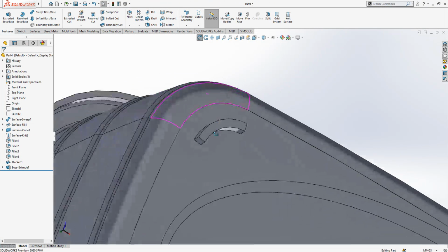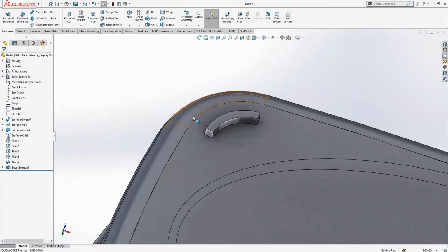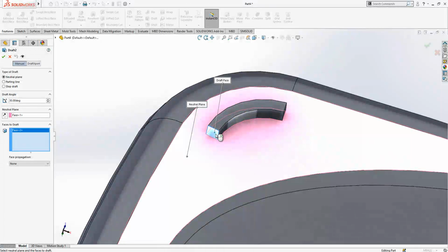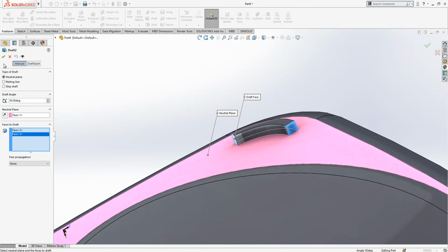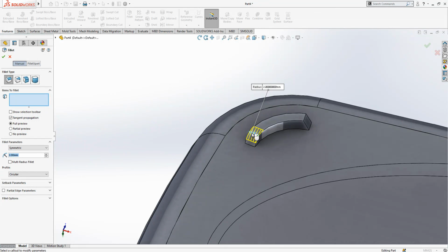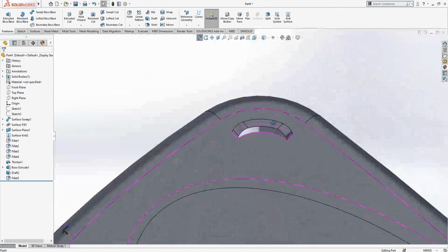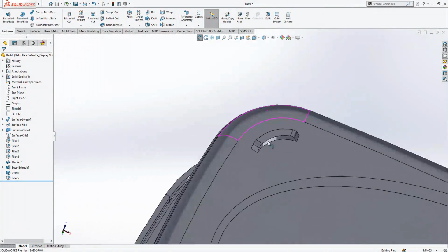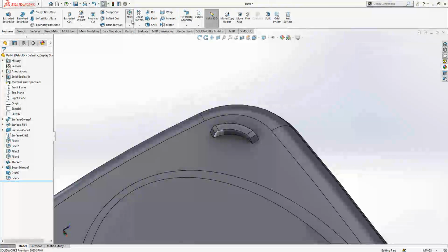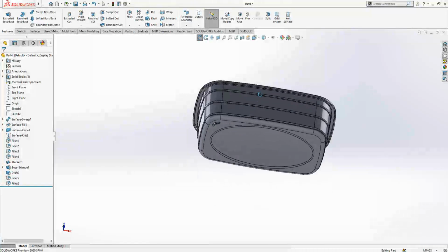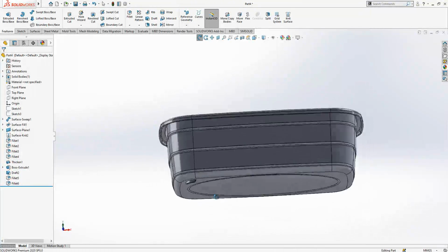So we made a boss extrude with 2 degrees, but I want to give these 2 faces here a little bit more angle. This is a neutral plane. According to what we are going to give value and the tangent, the draft angle is 30. It is quite nice, simple, and here now we have value of 2, something like this. I think I use in my own 1 because it is not measurable, quite small thing. So, and a little radius, again 0.2 on these tips. Yeah, it is all right, and this will be my little foot.